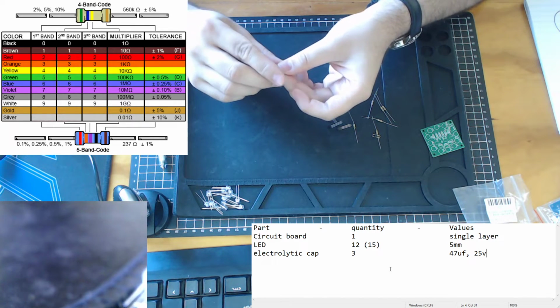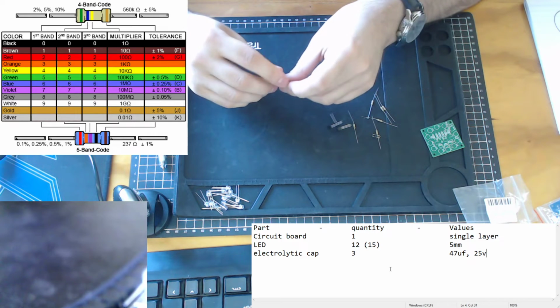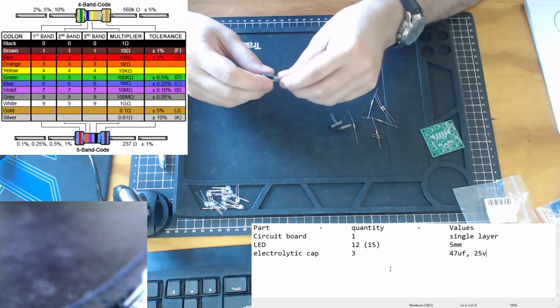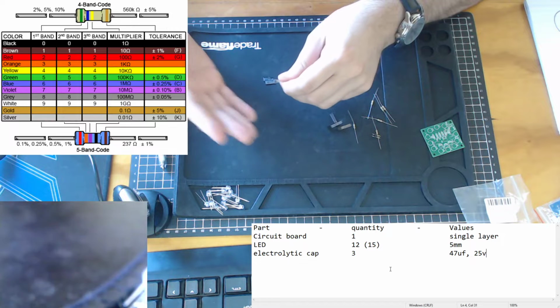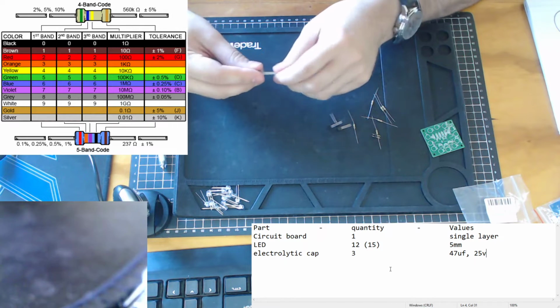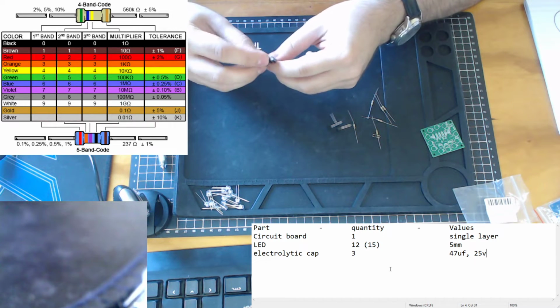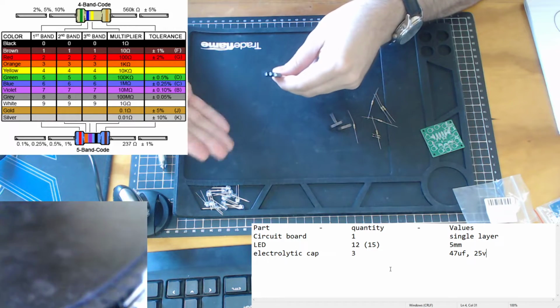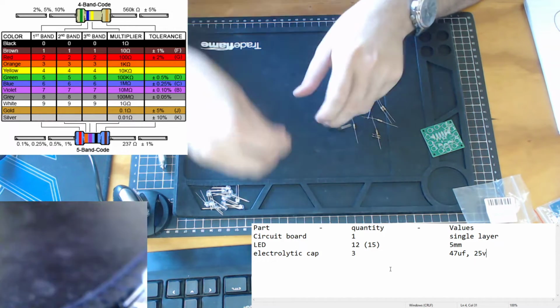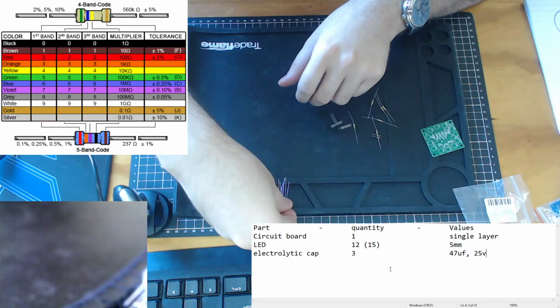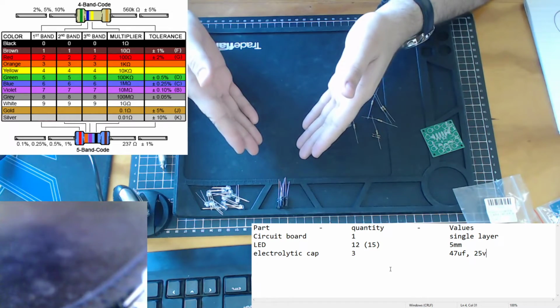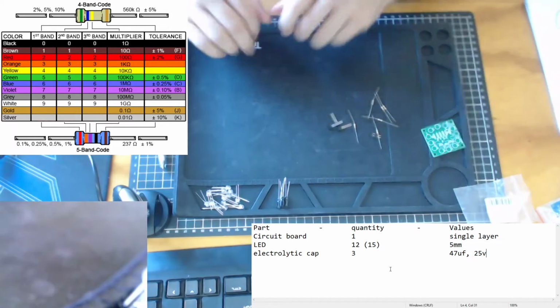When replacing capacitors, the most important part for the functionality of your circuit is making sure you get the right capacitance value, which is the microfarads, the µF. The voltage just means that if you're dealing with a voltage higher than what these are rated for, it could cause short circuits. So it's only rated at a certain voltage.